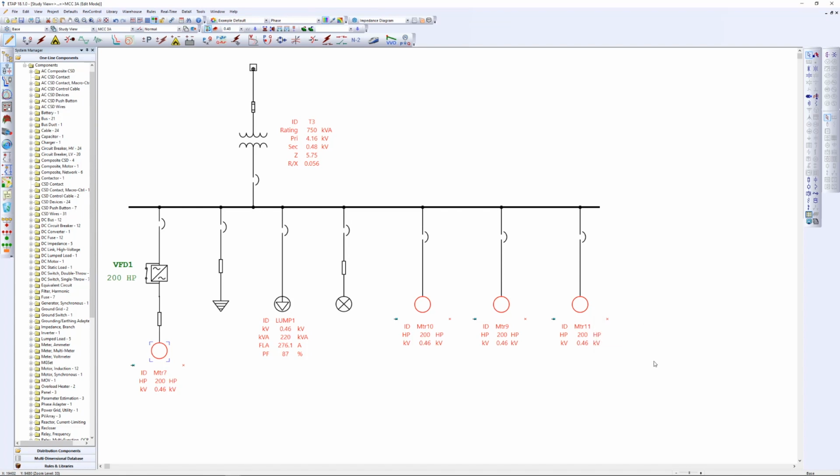The Copy Global Paste data was recently added to ETAP 18. You can do this through the OneLine diagram in the right click as I just did. Or I can do it with the Data Manager as well.